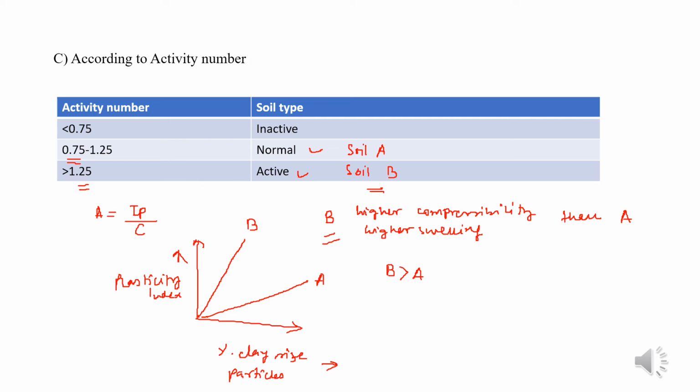and accordingly we can determine whether it can be used as a foundation material or for any other construction purpose. We already talked about a few of these in the previous slide, like how we can classify and tell about the consistency of the soil based on the numerical value of IC or IL. Also, suppose the liquidity index is less than 0. In that case, the soil will be very hard, or it will behave like a brittle solid, and when sheared it will fracture.